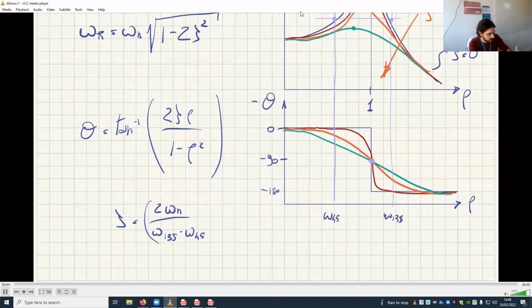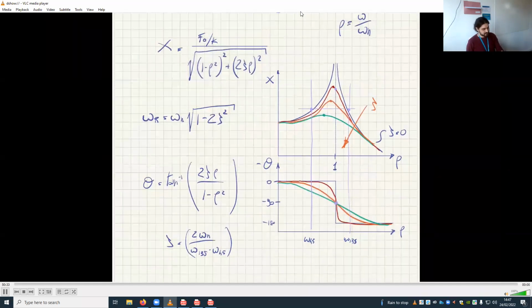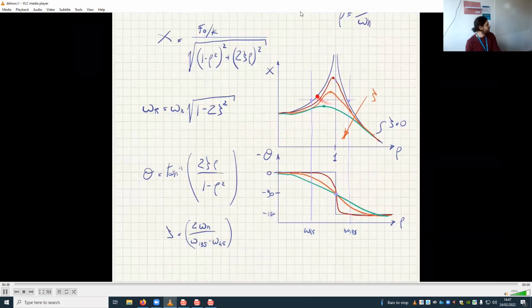So this is one other way to estimate the damping, looking at the forced response rather than the free response. Logarithmic decrement is only for free responses, because you let it vibrate and you see it die down, and you can see how many oscillations it takes for it to die down, or what is the ratio of two successive amplitudes. This way is a forced way. So you just extract the frequency response, and then looking at this ratio tells you how sharp is this peak. So you can estimate the damping ratio in that way. Okay, that's done for question one.